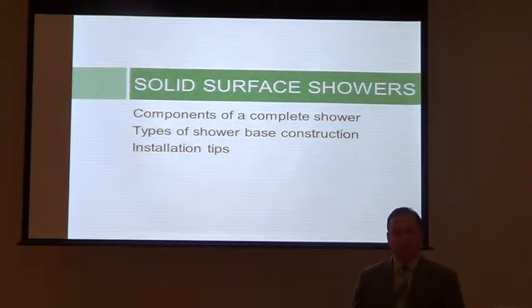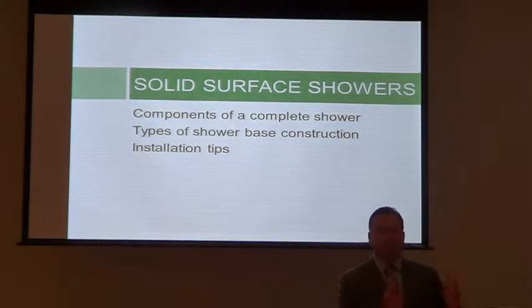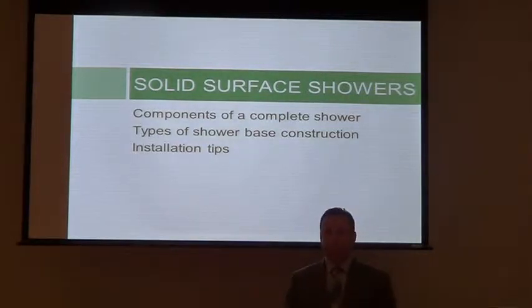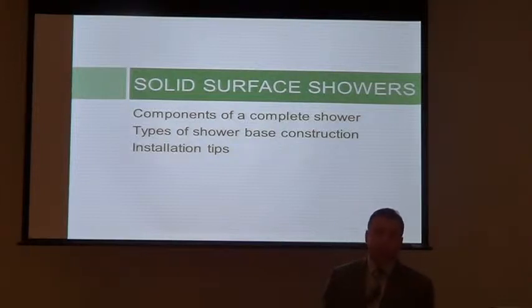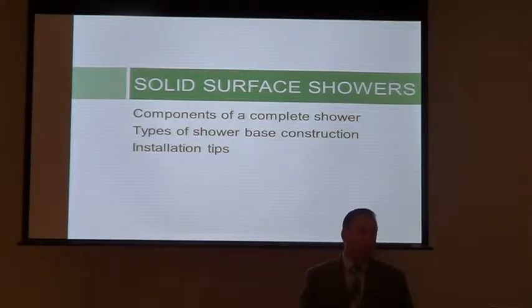So, general rule of thumb, if you think about how do I clean it, okay? I was taught this a long time ago. It's as easy as ABC, ammonia-based cleaner. That's the easiest way to do it. In today's healthcare systems, they have their cleaning protocols that are much more strict and stronger than we would use in our kitchen, and those protocols work just fine. I've put solid surface into healthcare environments for 15 years, and I've never once had a complaint. Okay? So, granted, every healthcare system has their own protocols, but whatever they choose to use works just fine.